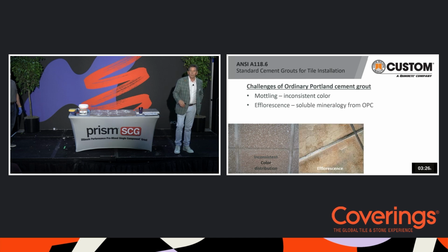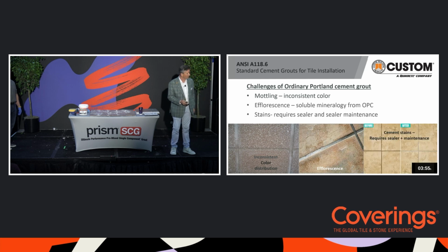Because it has Portland cement, it has the potential to create a condition called efflorescence. Efflorescence is simply soluble mineralogy that's in the ordinary Portland cement. So add the water, free up the soluble salts and mineralogy, but that solution comes to the surface, it dries and leaves that mineralogy on the surface. So concrete, brick, block, anything that uses Portland cement in the system has that potential.